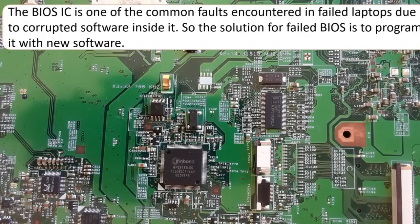So for the BIOS, if you want to check it, when you power the motherboard, you should check pin number 8. And of course, on pin number 8 of every 8-pin BIOS, you have to find 3.3 volts. Okay.